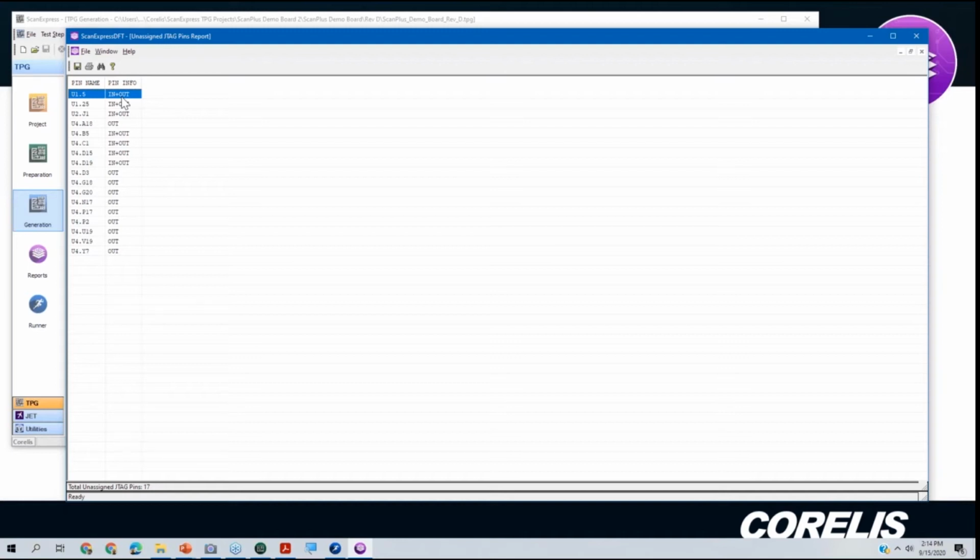If we think about what a boundary scannable device is to us, depending on your perspective on these things, it kind of is like an internal test instrument. We have 1, 2, 3, 4, 5, 6, 7 IOs just sitting there that we could be using for test. So we could connect these to something else. In the case of U1, this is a PLD, so we could program the PLD for that just to be a don't care, and then we can use it for boundary scan capabilities. In the case of this processor, we would want to make sure that it's not going to interfere with anything if we connect these up, but you could use these as almost additional virtual test points on the board. And that's what's great about that report.